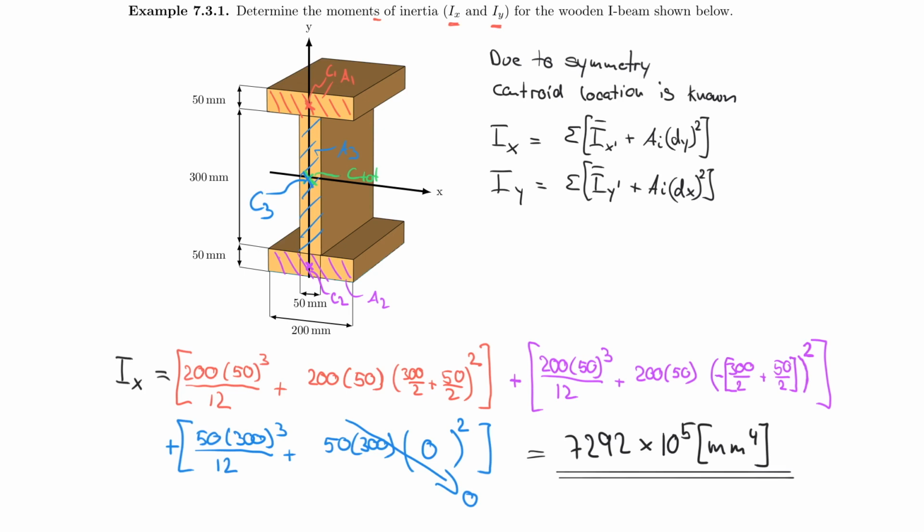But maybe even one mechanics class is not enough to do that. So the best way to get a feel for it, or to counterbalance that you don't have a feel for it, is actually find another way to break this down into different sections and calculate your Ix in an alternative way. So another way that you could do, for example, is you can calculate an entire rectangle and then subtract this rectangle and subtract this rectangle, because keep in mind that a summation can also be a negative summation, right? So you can have the entire rectangle and subtract something. However, I promise you that this is the right answer for now, and we can move on to